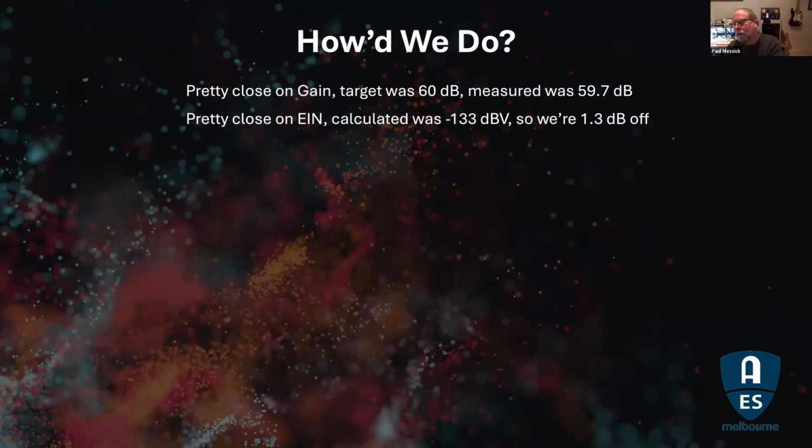But that means that I built into the measurement the noise of the 150 ohms. If you were to measure it with a lower impedance source, it would be better. And in fact, going from just calculating it, if you went from the 150 to the lowest that the AP will do, which is 40 ohms, that's about 2 dB.